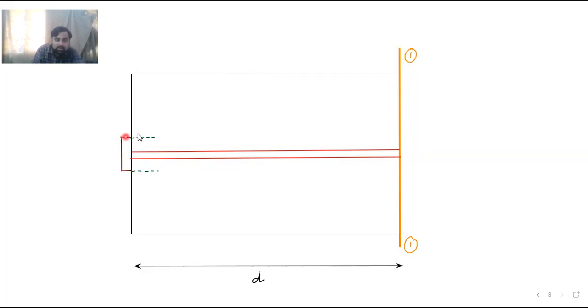So we are considering the dispersion from this end only. So here the dispersion will be like this. Okay, it will be like this. So this is the dispersion of the compressive stresses, and this angle according to Magnel is 45 degrees.